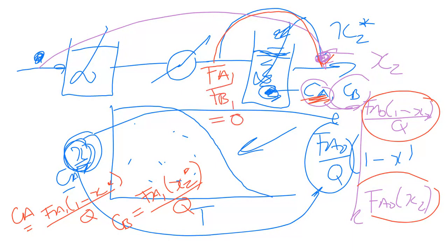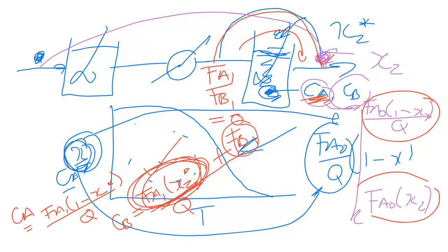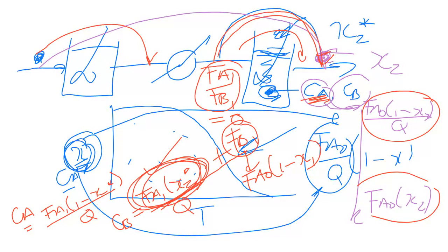So the molar flow rate of B that you must use there is equal to Fa1 times X2 star, whatever is formed, that is correct. That's the amount that is formed in that reactor, plus Fb1. And of course, Fb1 I can write in terms of Fa0 times X over reactor 1. Please be careful. When you use the incremental approach, make sure that the Fb coming out of here, which you use to calculate the concentration of B, is correct.